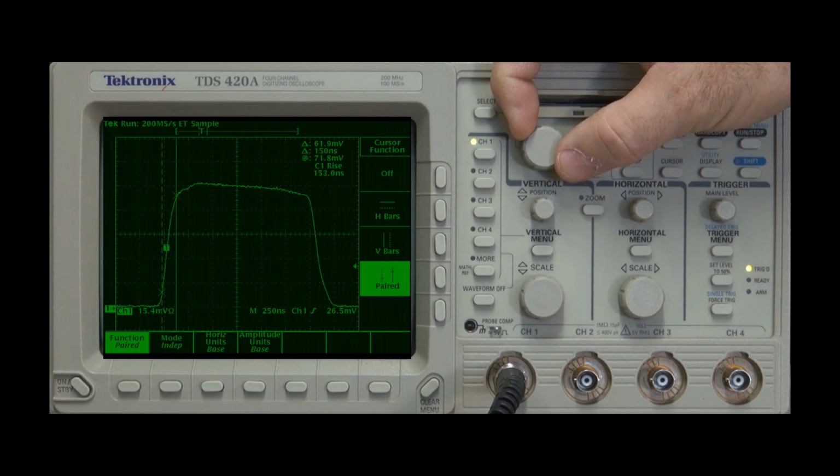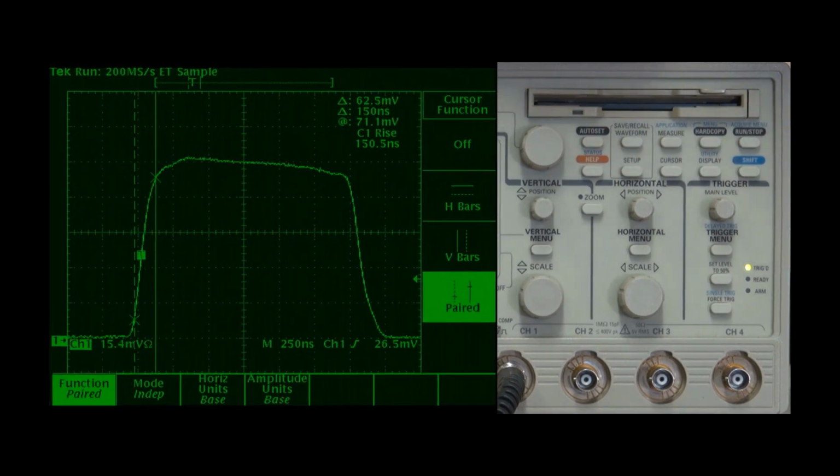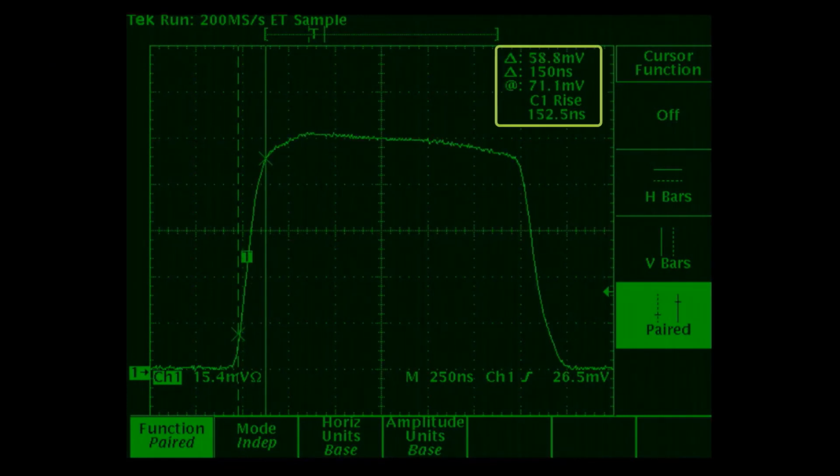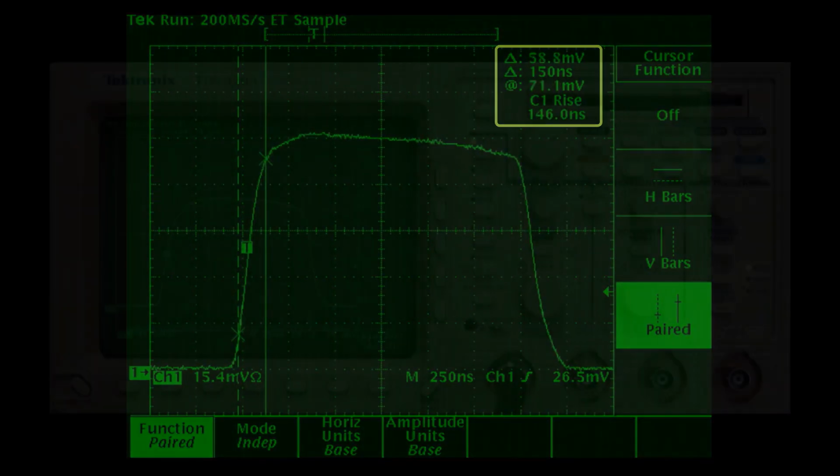And then we're going to measure the 90% point, half a division between the 80 and 100, or between the 4th and 5th division. And we've got our 90% measured. Now we're not moving our cursors, so that measurement's static, and you see it's showing 150 nanoseconds. Our automatic one is currently moving around a little bit because it is moving with the waveform that it's measuring.